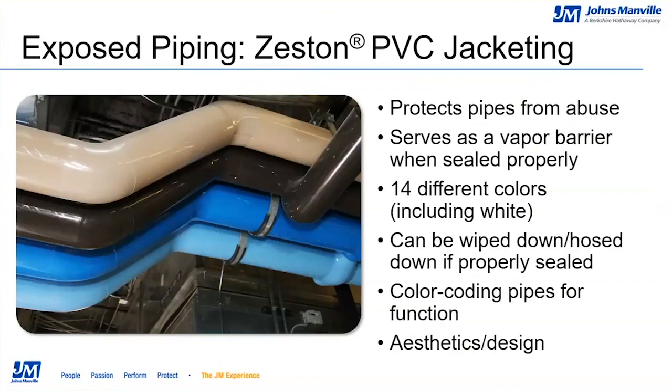Zeston PVC jacketing not only protects pipes and insulation from abuse by serving as a hard barrier between the insulation and the occupied space, but it also serves as a vapor barrier when sealed properly. This can be crucial for a system that is running at or below ambient temperatures. Zeston PVC is an excellent choice for many aesthetic applications because it is available in a wide variety of colors. There are 14 different colors available, including UV-resistant white, in both 20 and 30 mil thicknesses.